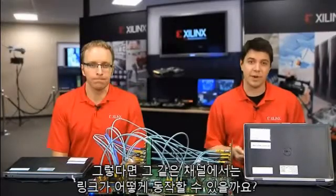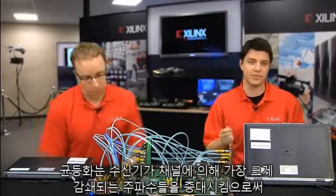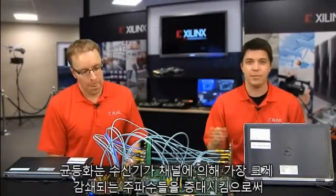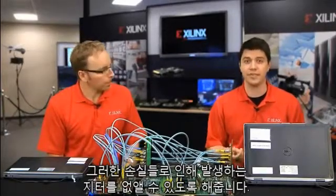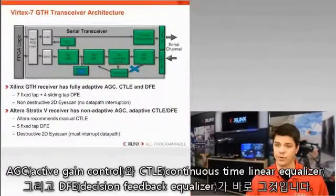So how can a link possibly work over such a channel? Equalization. Equalization is what allows the receiver to give a boost to those frequencies most attenuated by the channel, thereby removing that jitter that resulted from those losses. In the best 10 gig systems today, there are typically three main components that comprise the equalization circuitry: the active gain control, or AGC, the continuous time linear equalizer, or CTLE, and the decision feedback equalizer, or the DFE.